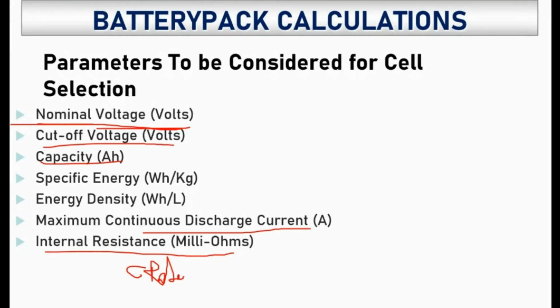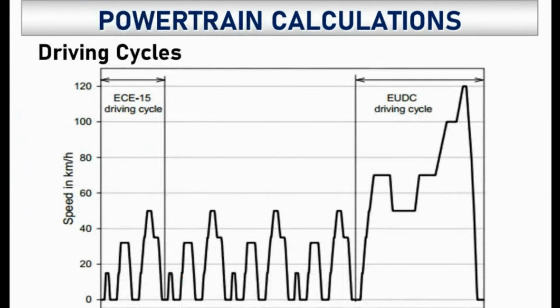And when we know that my motor should get 2 kilowatt of energy, we choose a battery pack which should be capable of providing the energy demand of the motor. This is how we do a selection of components, especially in this case the selection of the battery and the motor.